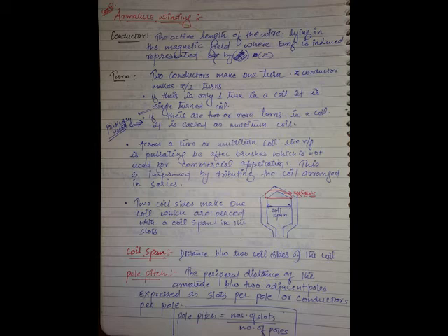But one thing you will observe in common: under a pole, always there are 180 electrical degrees. Observe this. Under a pole, it may be north pole, it may be south pole. Let the machine contain 2 poles, let the machine contain 1000 poles. Irrespective of the number, always under a pole there are 180 electrical degrees. Yes or no? Why I am discussing all these things: pole pitch means 180 electrical degrees.